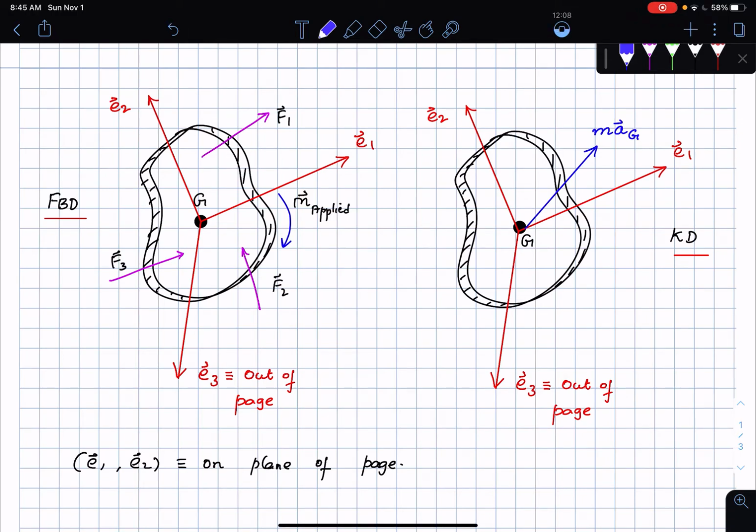And then depending on what the angular velocity direction of the disk is, or if I don't know, I'm just going to assume a direction. I'm going to say that, okay, there is a torque, which is Ig times alpha, where alpha is a vector quantity, as you can see here. Ig is the mass moment of inertia about the axis coming out of the page. So that's essentially what I have here.